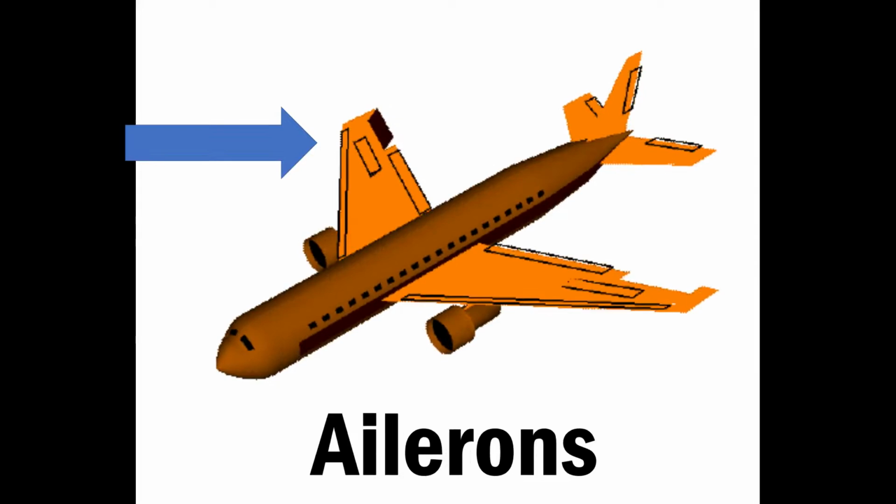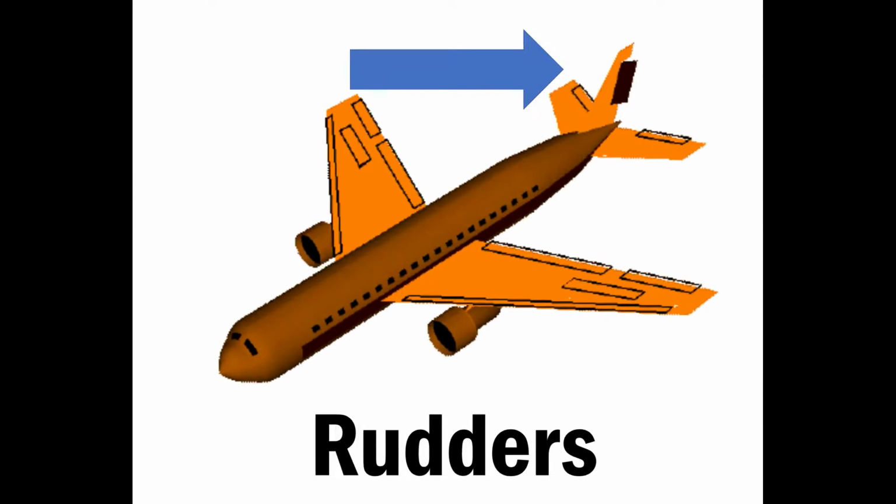Control surfaces are divided into 2 categories: primary and secondary. Primary control surfaces include elevators, ailerons, and rudders. Engineer George Cayley was the first to utilize an elevator on his glider. His glider featured a horizontal tail that tilted up and down to deflect the air in a way that would cause a pitching moment on his glider.